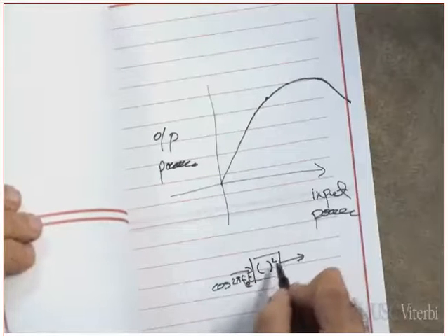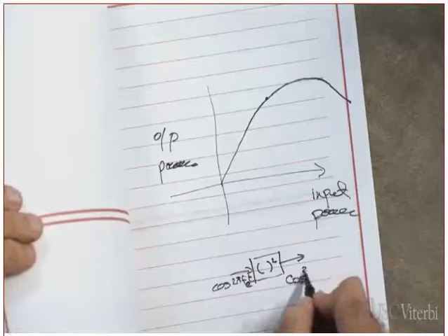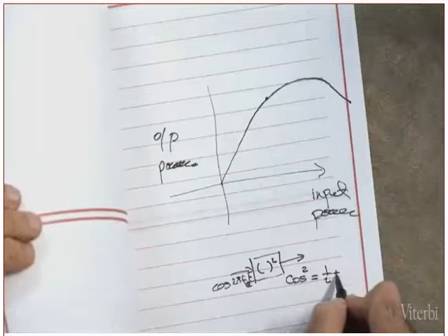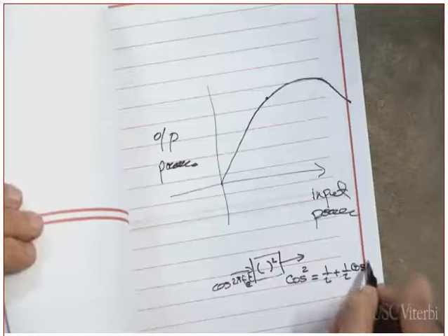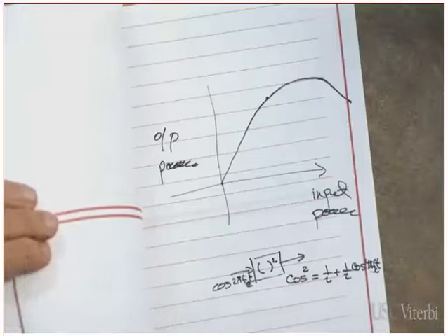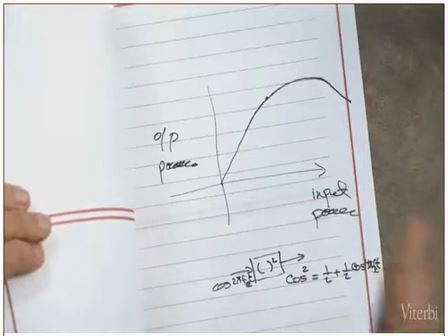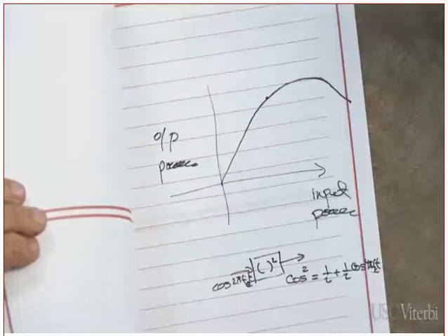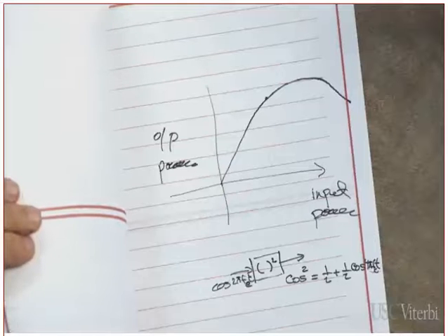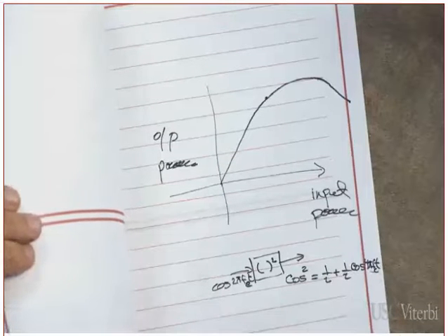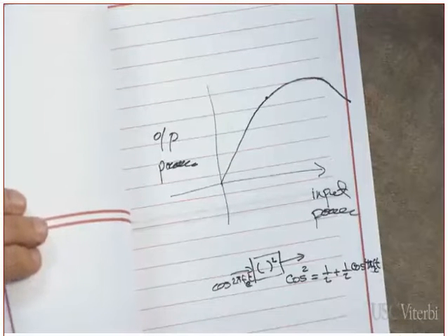I have cosine square, which is equal to 1/2 plus 1/2 cosine 4 pi fct. Did we create the second harmonic? Could that second harmonic interfere with other devices, with other transmitters operating at that other frequency? That's what I meant by generating all of these side lobes and stuff.